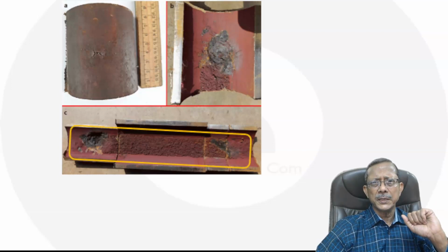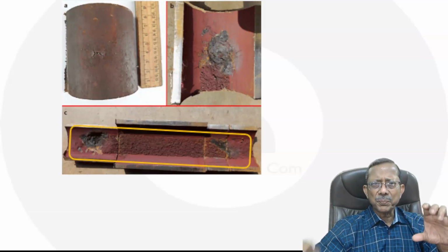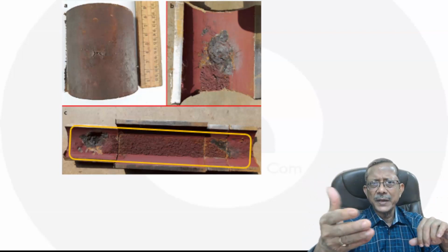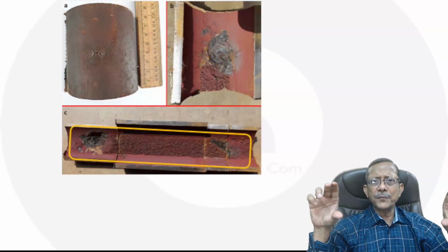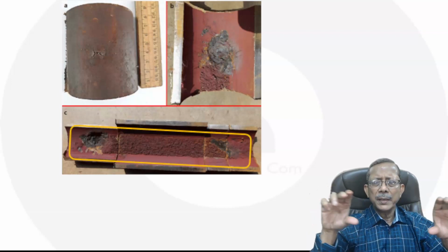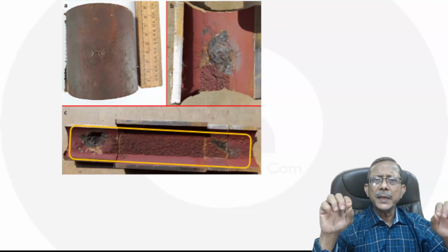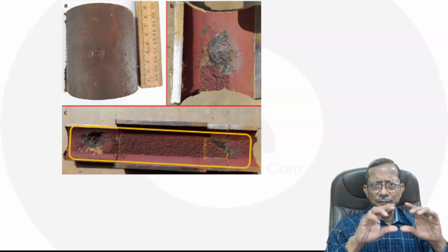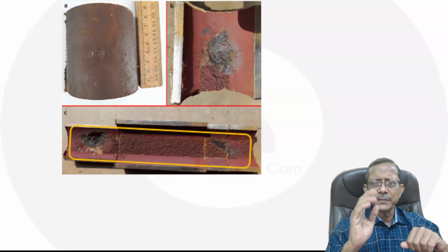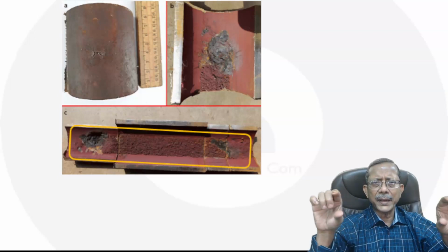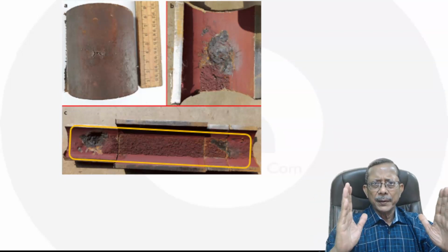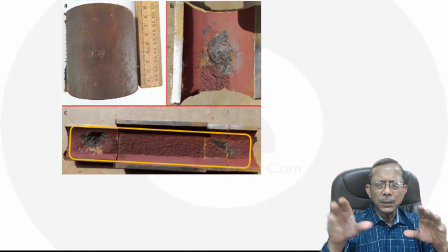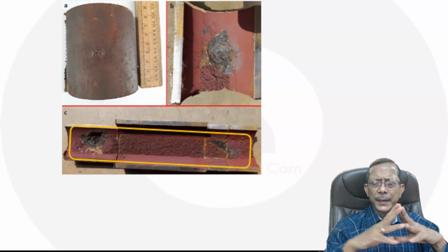And in one of the tube components, there was a clear indication of a strip type of corrosion area at the 12 o'clock position, facing the fire side. This is a clear indication of film boiling that has taken place in the system, right? Once film boiling takes place and steam blanketing occurs, it forms almost two parallel lines, a strip, and it is almost a signature of a film boiling condition. And corrosion is indicated there, right?